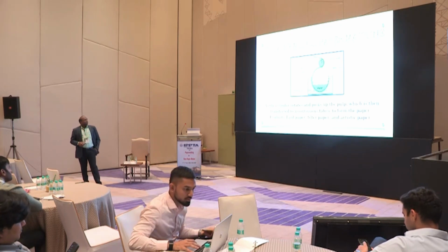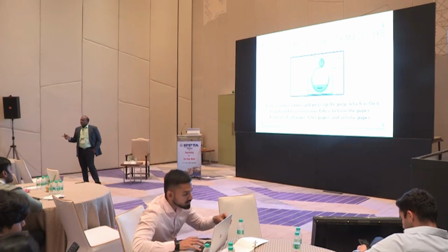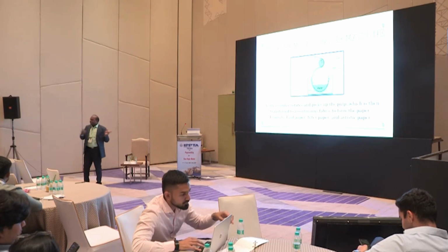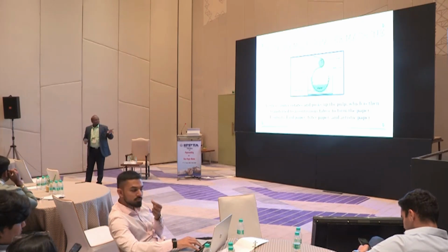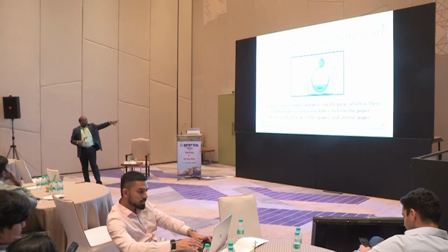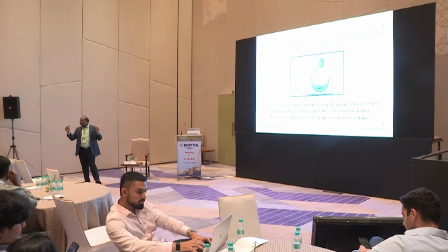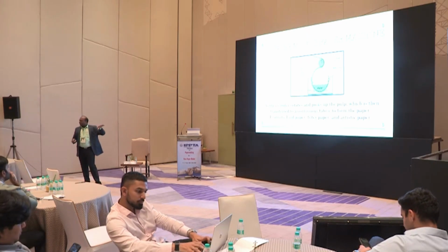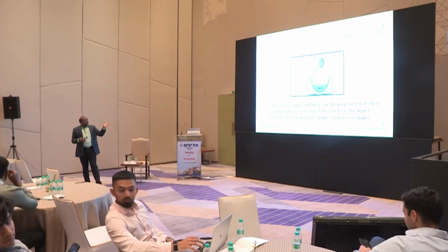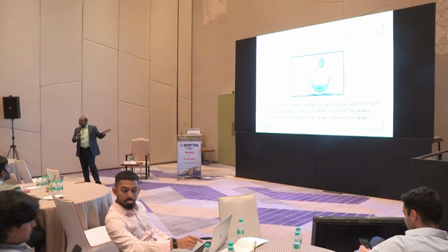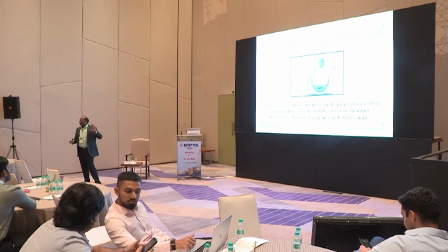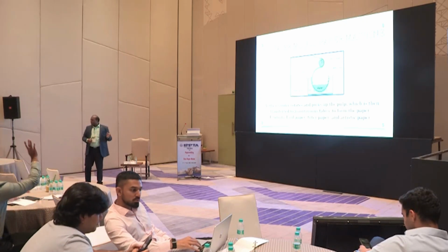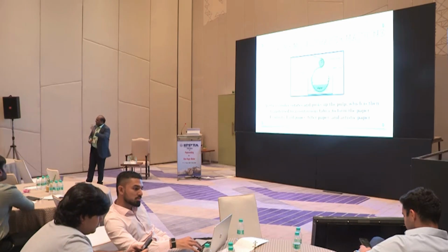And this is the cylinder mold paper machine, where yesterday morning we used to discuss the duplex board. The sir told that we have 6 to 9 cylinder mold machines. Here there will not be a wire part. There will be a tub and a roll will be rotating. Small holes will be inside the rolls, and as the roll rotates, the fiber will catch up and transfer to the press rollers. So here there will not be any wire. It's a peculiar design. It's an old technology, but specific products can be manufactured by this.